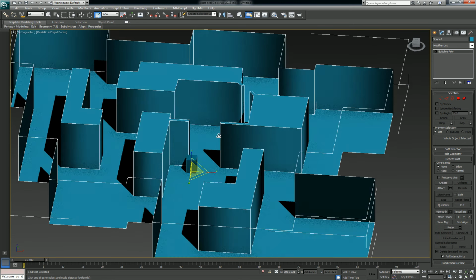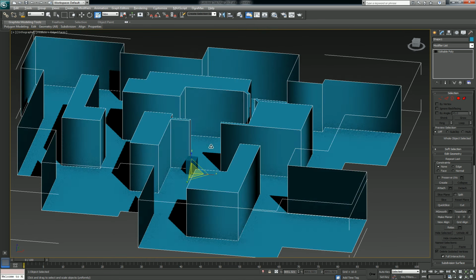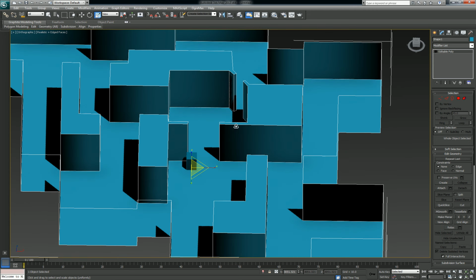So you might notice from time to time that a model might disappear off of the scene, and it's usually because the object that is trying to be rendered is smaller than the rendering threshold, meaning where the engine culls objects. So if we're at a particular view angle, something that's a building in the background might be the size of a button, and it gets excluded or culled because of that.